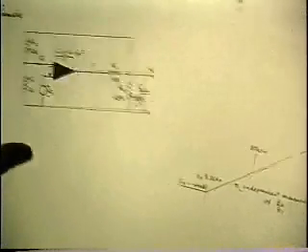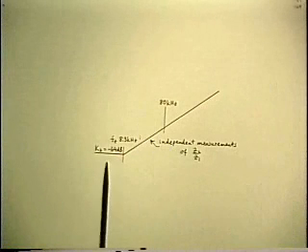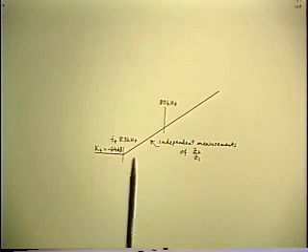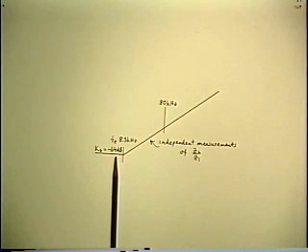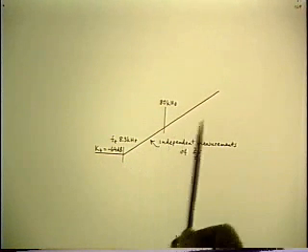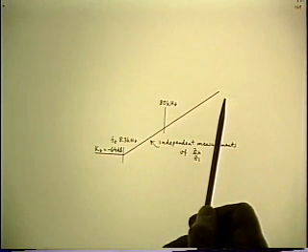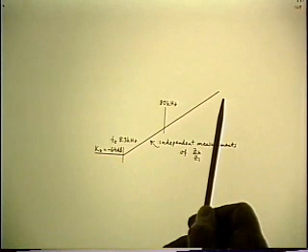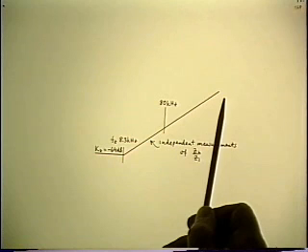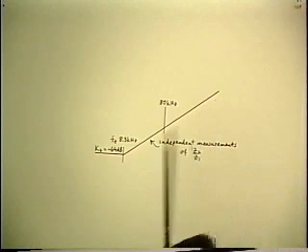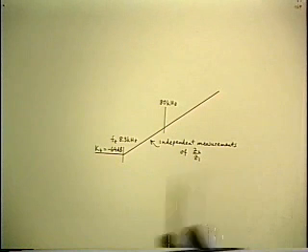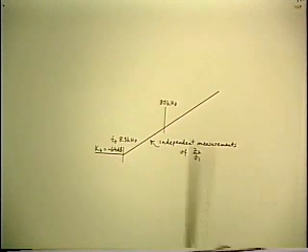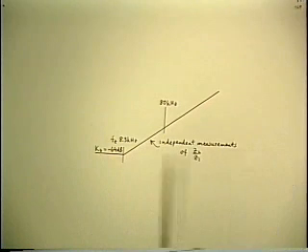And it's this. Z2 over Z1 is a small number, K sub Z, minus 64 dB. That's less than 1 over 1,000. But it comes up at higher frequencies. Not because Z1 goes down, but because Z2 goes up. In other words, the output impedance of the op-amp rises at higher frequencies. In fact, it looks inductive. Again, an example of where you get the property of an inductance, and there's no real inductance there. But it's to do with the internal structure of the op-amp. It behaves inductively.